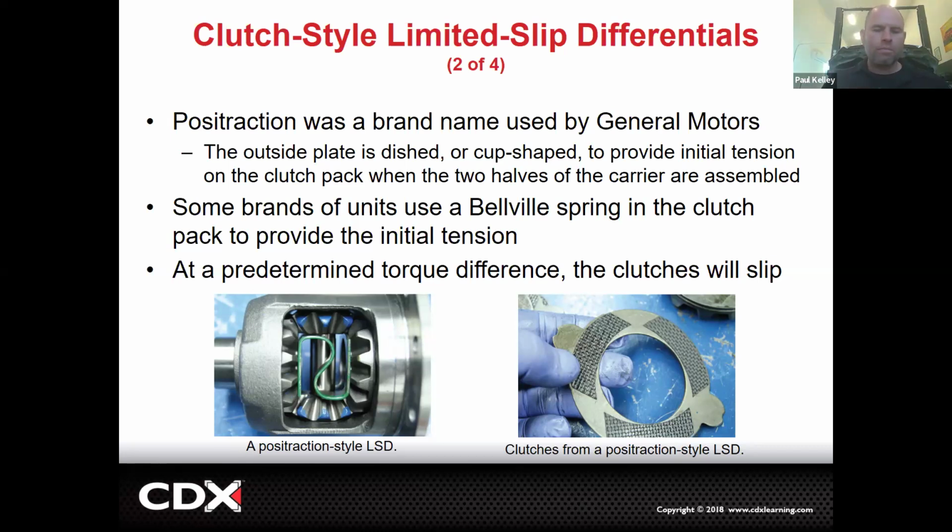The negative, though, is they do have clutches, and those clutches do wear, and those clutches do require a special type of lubricant that has a clutch additive. So if you put regular gear lube in an LSD with clutches, those clutches are going to stick and bind.